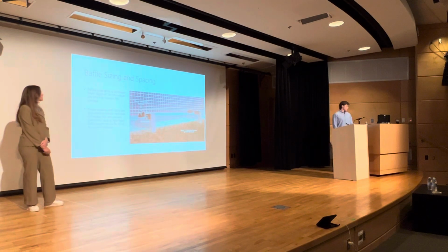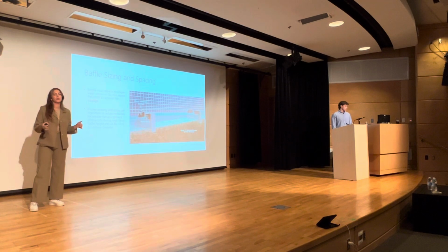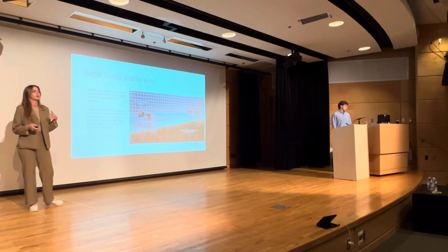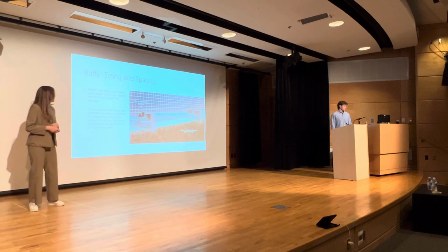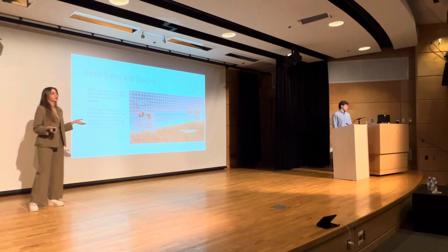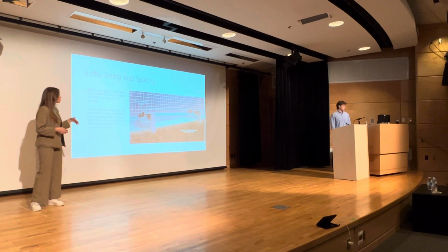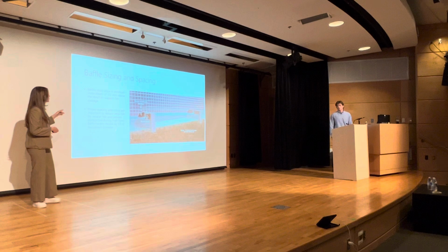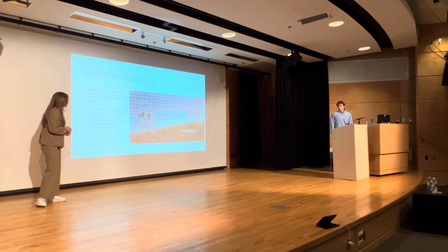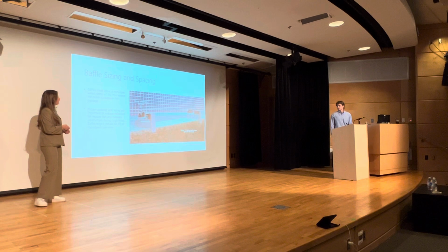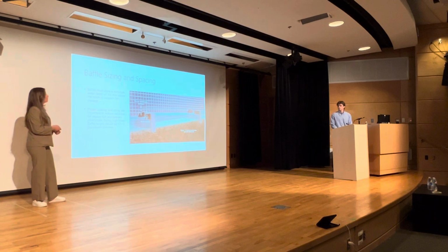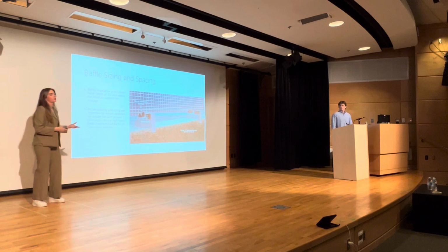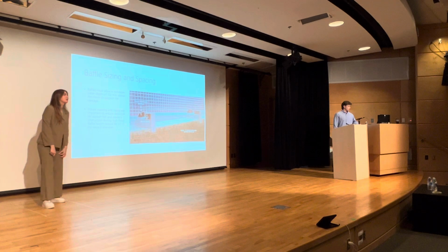This is our baffle sizing and spacing. The baffles must allow for a minimum water depth of 100 millimeters above the notch to allow for the fish to go through them. This is important for the reduction of velocities, and that's the whole point, so the fish can go through them. This is our notch depth, which is from the top of the baffle to the top of the water elevation. And this is our drop between the baffles. If you can see that line there, it's just the height difference between the previous and the following baffle. So this notch depth must be 50 millimeters bigger than this, as per DFO specifications, which is the Department of Fisheries and Oceans.